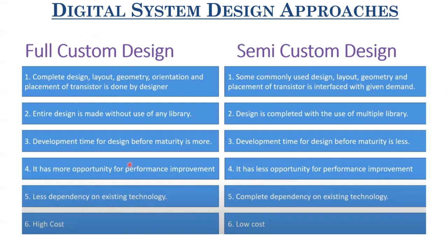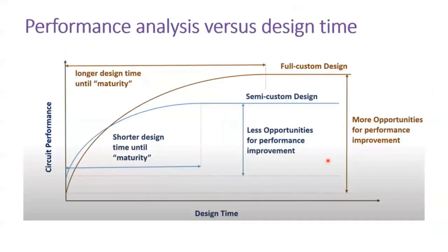And full custom design requires more manual labor, and skilled manual labor is much more costly compared to automated designs or automated software or their licenses. So full custom design is high cost, whereas semi-custom design is pretty low cost. Now, let us look at the circuit performance as a function of the design time for two approaches, full custom design and semi-custom design.